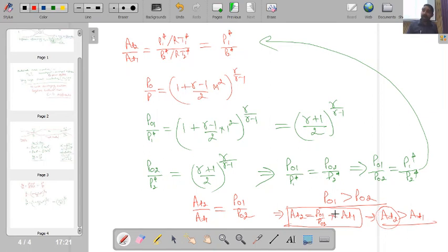This throat area, one another important point is this throat area, whatever we have calculated, we calculated by considering that my test section is already having the Mach number at the desired condition. Okay, so if a supersonic wind tunnel is already in operation and giving us the desired Mach number, then my throat can work at this area.